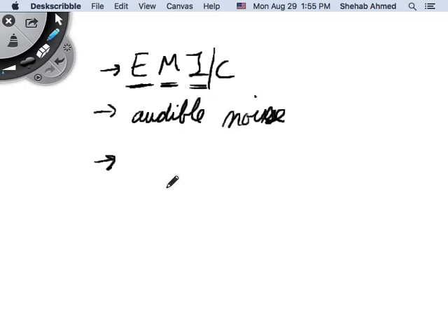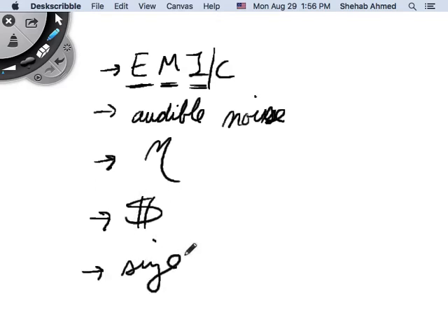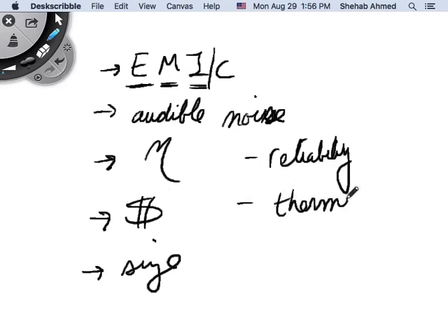Power electronics is the same. You're causing all these variations in voltage and current waveforms, and you have inductors and capacitors charging and discharging, which will produce some noise levels. So converters will differ based on noise level, efficiency, cost, size, reliability, thermal aspects, and dynamic response.